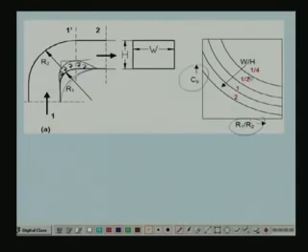And you can also see that for a given radius ratio, as the aspect ratio is increased, the dynamic loss coefficient reduces. That means, let us say we compare two ducts with the same width but different heights. You find that this will give you less dynamic pressure drop compared to this. That is what is obtained from this particular graph, and equations are also available for estimating the dynamic loss coefficient Cb in terms of R1 by R2 and the aspect ratio.